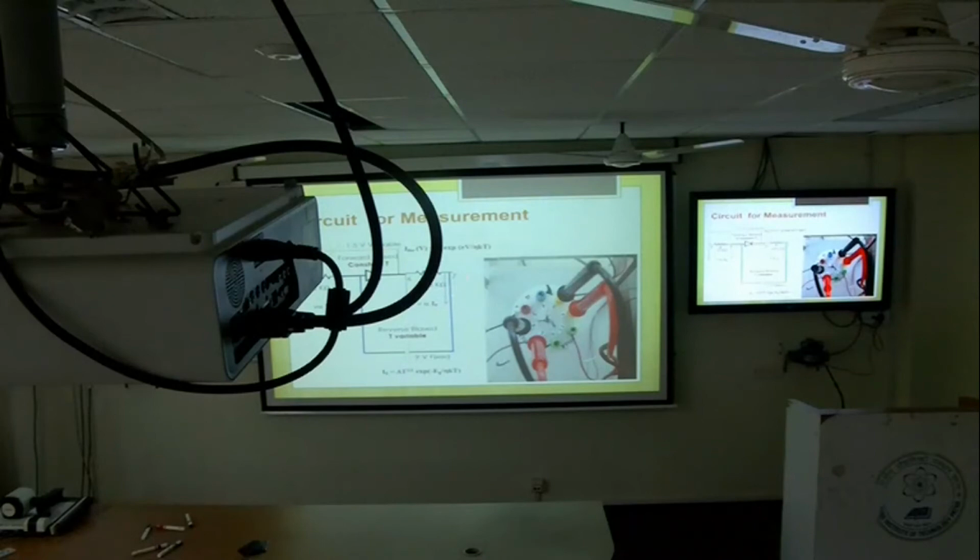And secondly, you can have a voltage drop here, so you can easily measure the value of V. The PT100 is shown here, on the upper side of the insert, connected here, and this diode and this one are connected here. The 2 kilo ohm resistor is connected here. So the value of the voltage drop will be found from these two terminals.